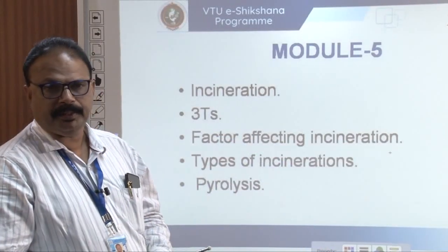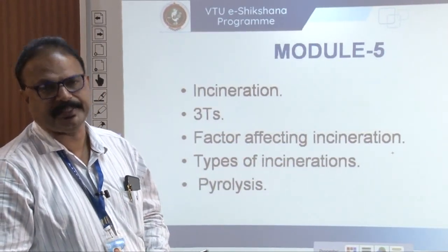Okay, we have completed all the other modules. This is module 5. In this we will study incineration, which is the burning of waste at high temperature, the 3T process (time, temperature and turbulence), factors affecting incineration, types of incineration, pyrolysis, design factors, and waste to energy. So many parts we will study in this module 5. First we will start with incineration.